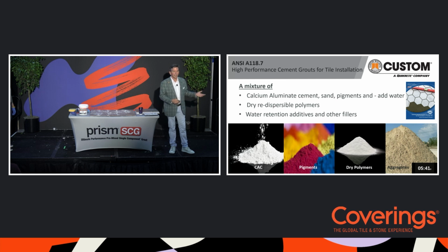So the calcium aluminate is going to dry much faster. It's exothermic, it has a heat of hydration. That's what gives a much better color distribution throughout that. And the calcium aluminate itself cannot contribute to efflorescence because it does not have the mineralogy to do so.